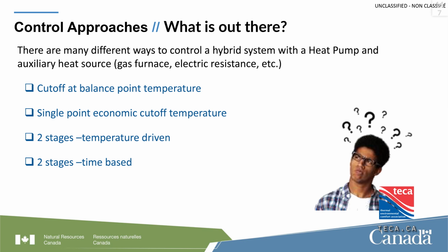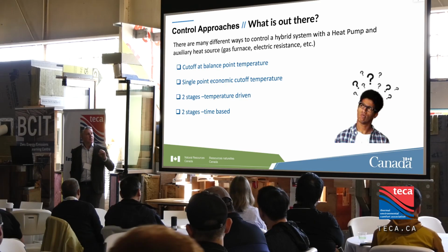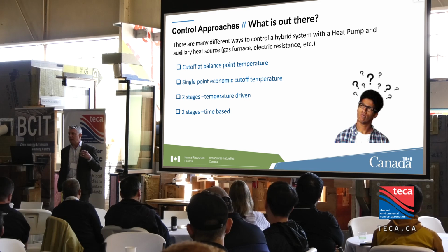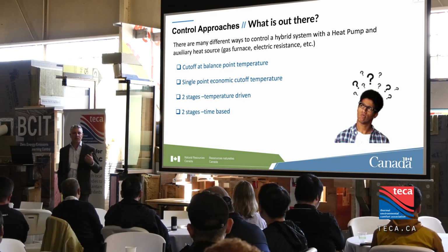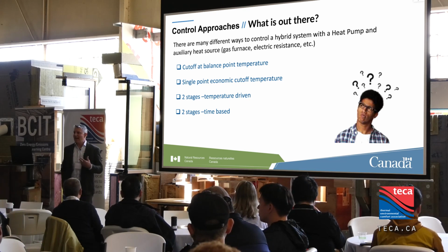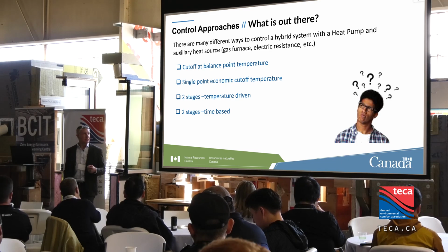The next one is a single point economic cutoff temperature, and today we're concentrating on fully electric systems. This concept would probably come in mostly handy when we have a dual fuel gas backup system. As part of NRCan's tools, which we're going to dive into after this session, there's a way to have the tool tell you at what temperature it is most economically sound to switch to the gas backup.